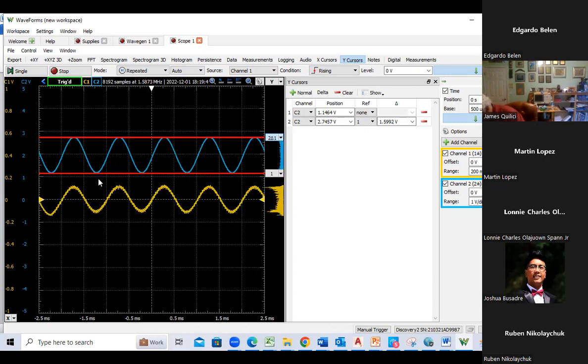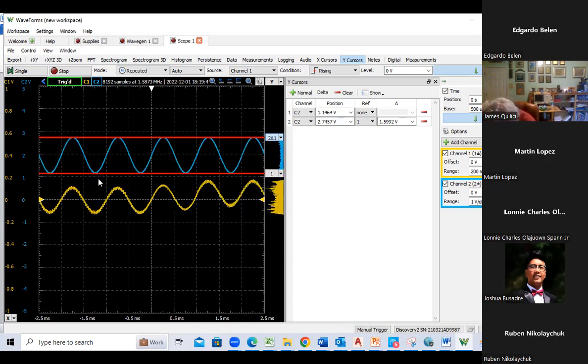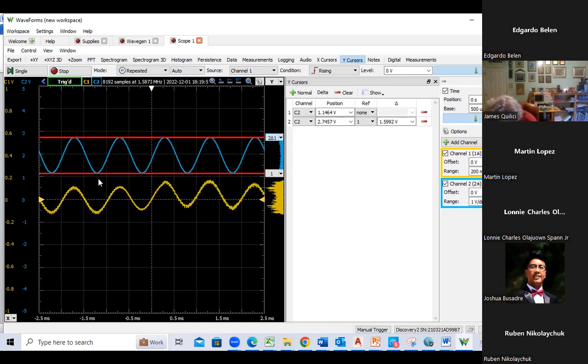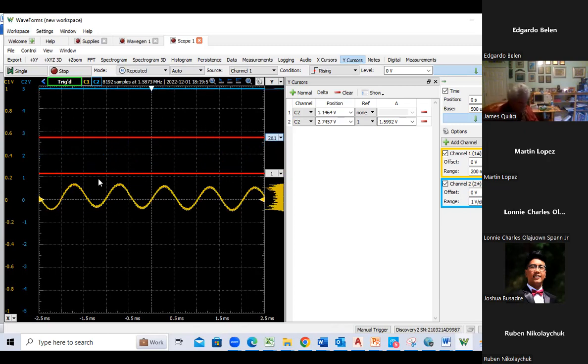So right now in my emitter, I think I changed that to red, brown. What did I change that to? Oh, that's 150. Yeah, that's red, brown, green, brown, 150. So I'm going to switch that now to 120 and see if that does it for me. So I need brown, red.